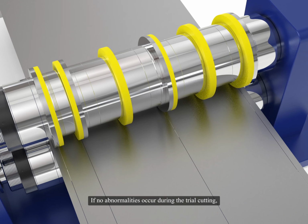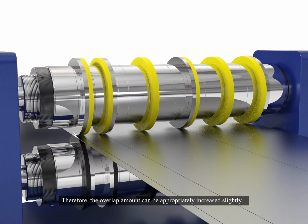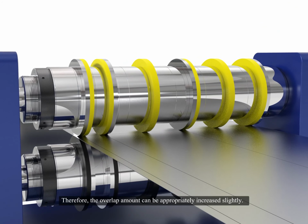If no abnormalities occur during the trial cutting, considering that the formal cutting speed is significantly higher than the trial cutting speed, the upper and lower arbors will deform to a certain extent under high-speed cutting conditions, which may easily reduce the overlap amount in the middle part of the arbor, and there may even be a problem that the middle coil cannot be cut. Therefore, the overlap amount can be appropriately increased slightly.